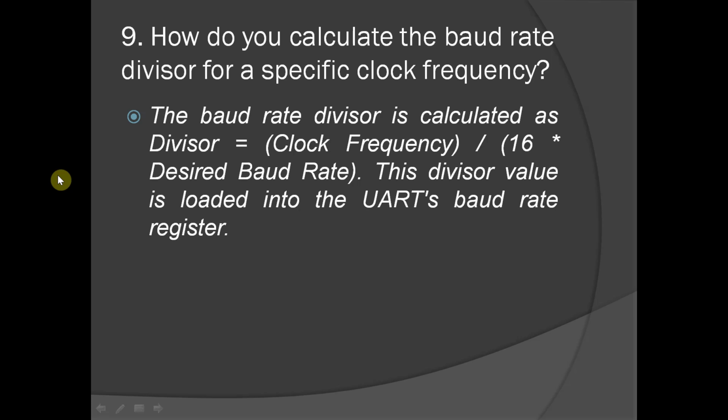If we do it like that, it will be asynchronous, right? And there will be a mismatch. There are chances of data mismatch in asynchronous communication. But we may use asynchronous communication also. If we want, we can work both modules, transmitter and receiver, with different baud rates. In that case, we can use CDC techniques, and we can also use a FIFO.